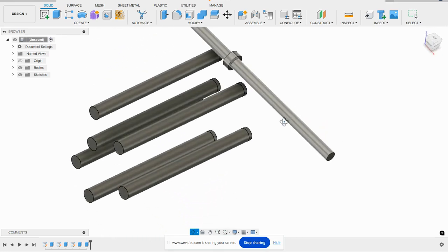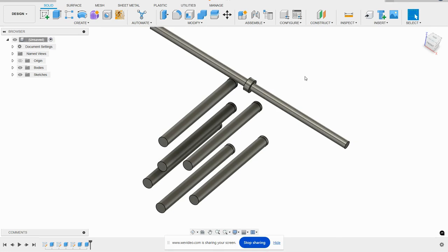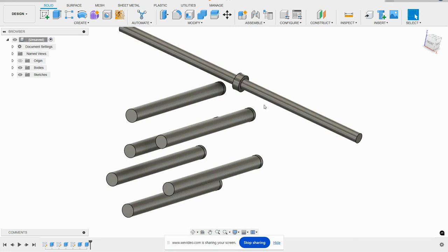All right, and here is why this is kind of looking the way that it does. Here in just a second, we're going to use automated modeling. And with automated modeling, we're going to be talking about faces that we want to connect. And we're going to then be talking about bodies that we want to make sure we avoid. In order to sort of keep the structure right and allow for things to go into these different positions, we need to make sure that there's plenty of room above this. So I'm kind of working this as obstacle geometry on top of those placeholders and obstacle geometry where the hole is going to be for the necklace. All right, so watch what I do with this.